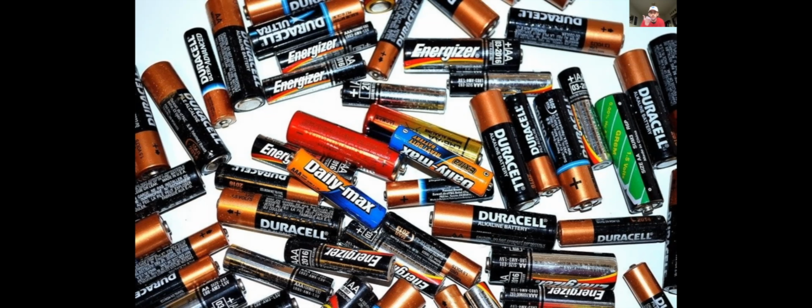You need to make sure that you don't explode them by overcharging them. Oftentimes this will be handled by separate circuitry that's either integrated into the battery or part of a dedicated battery subsystem or power subsystem that has the circuits just to make sure that you're not overdriving them. But basically, the command and data handling system needs to be able to draw power from the system and direct the power system.